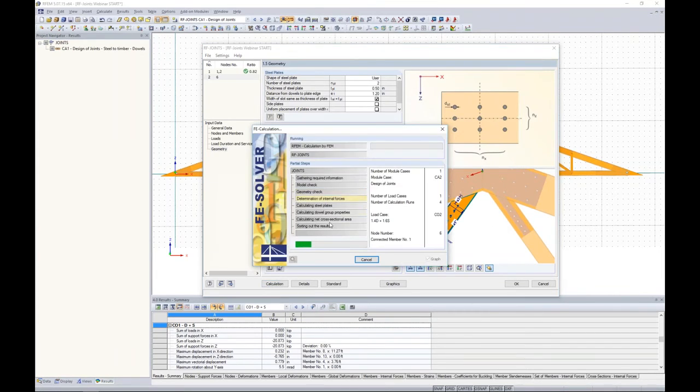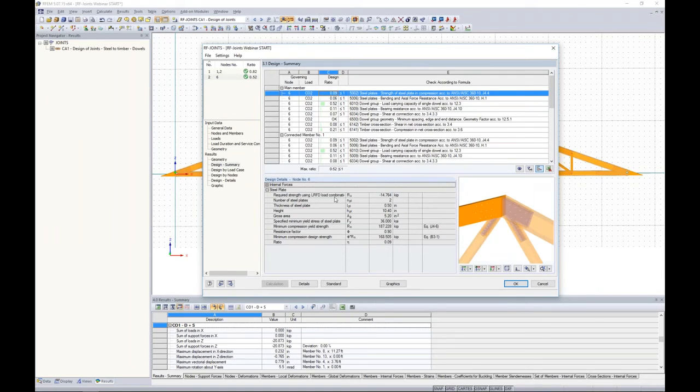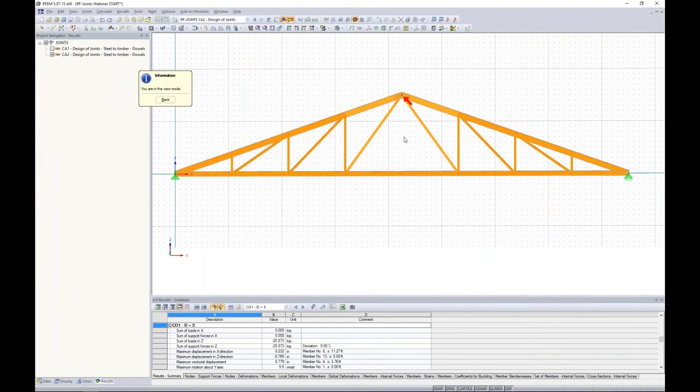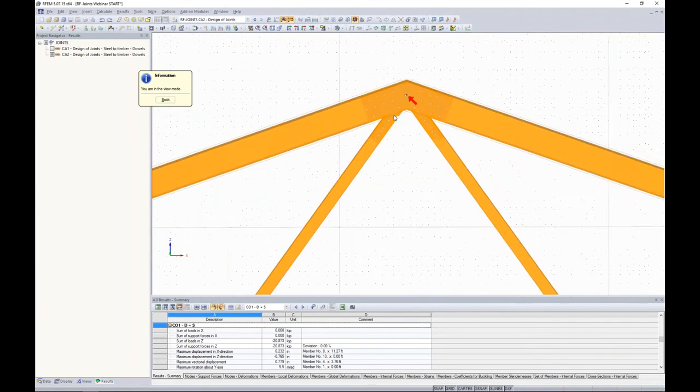Now we're ready to run a calculation. So again, it solves rather quickly. You can see that this brace connection went over a little bit better than the last one. We have a controlling code check of 0.52 here. So everything looks great in terms of that. Again, we can view everything graphically for this connection here.